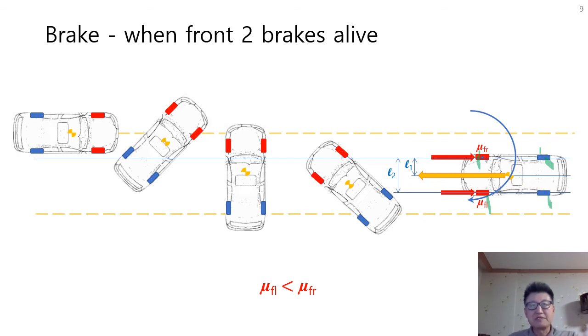We have to know that friction coefficient is different at each tire contact patch because friction coefficient is a function of tire and road surface properties, having a variety of spectrum. Therefore, brake forces are different at each side, even when vertical reaction forces are the same at both sides, because friction coefficients are different from each other. Then, let's continue our question. What happens at the panic brake?